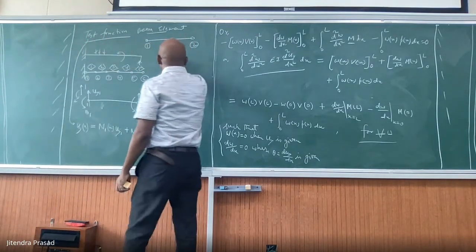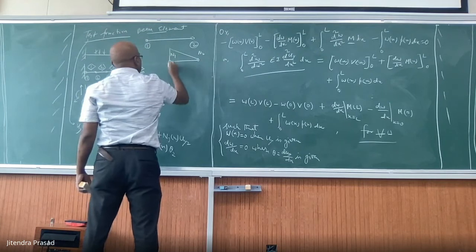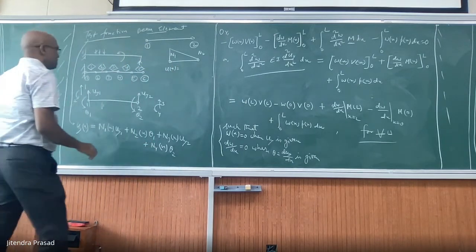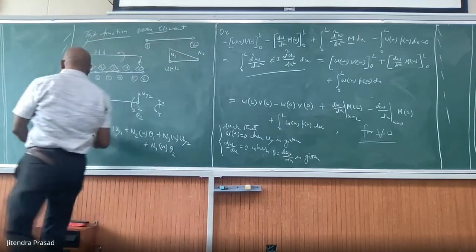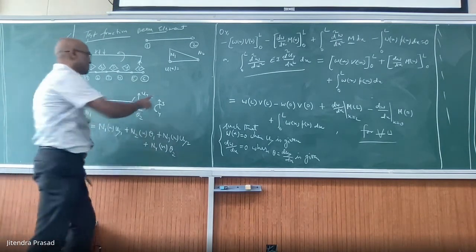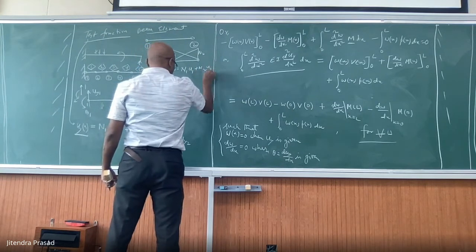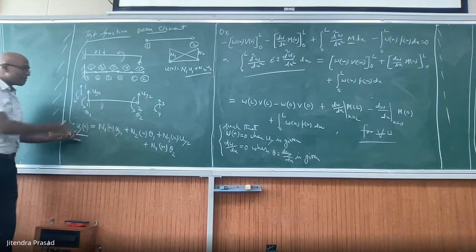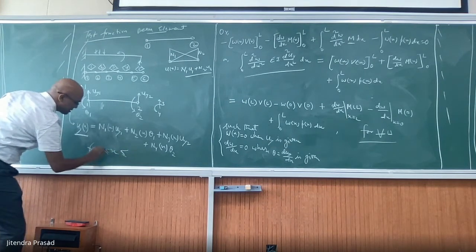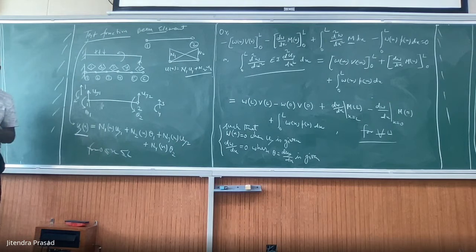Earlier, if you remember how we did, you had n1 here and n2 here. So you say ux is equal to this, and now this is uy. This is defining for the whole thing, not just for one place. The way you did ux for the 1D problem, you said n1 u1 plus n2 u2. This is only one equation that defines uy for the whole thing, for x from 0 to l. It's defined for all of it. So this is how you define uy(x) equal to this. Simply, from here we get everything.